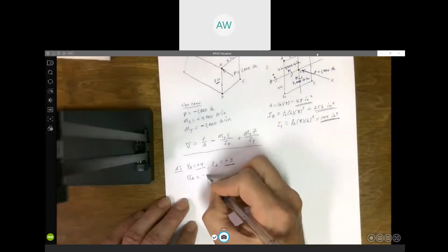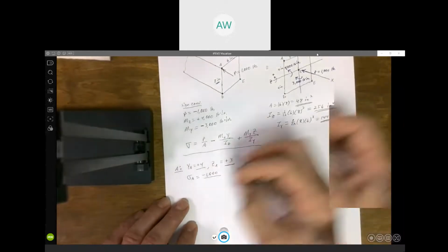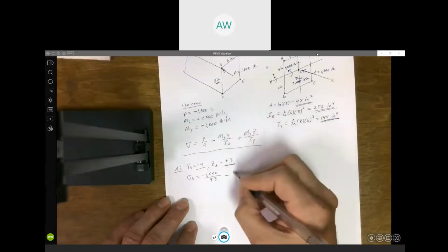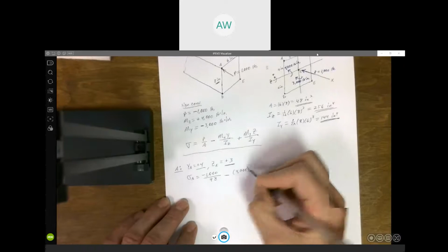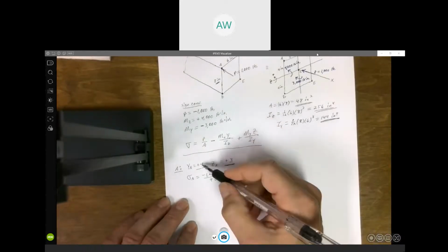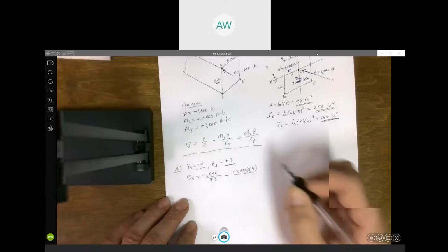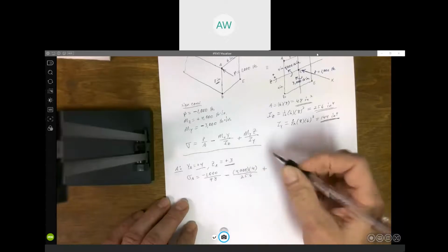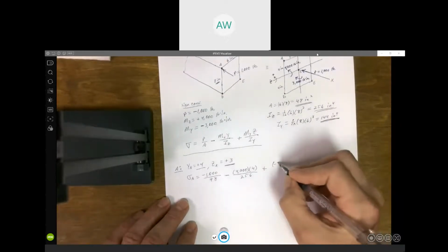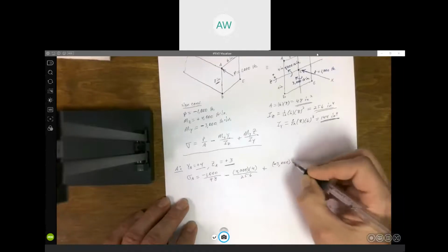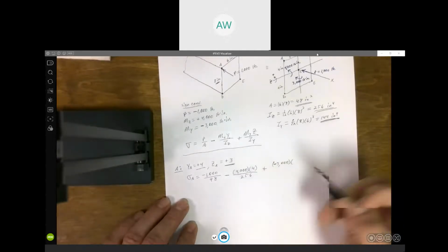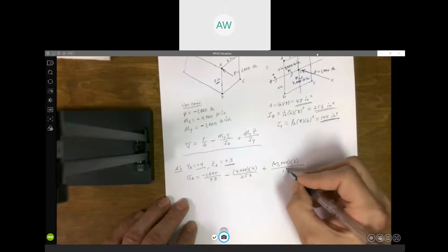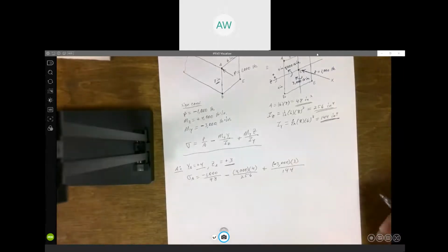We just plug in the formula to get the stress at A. We've got P is minus 1,000. Our area is 48, minus Mz was a positive 4,000. Y is positive 4. Iz is 256. And plus My is a negative 3,000. Z for point A is a positive 3. And Iy was 144. And we add those up.